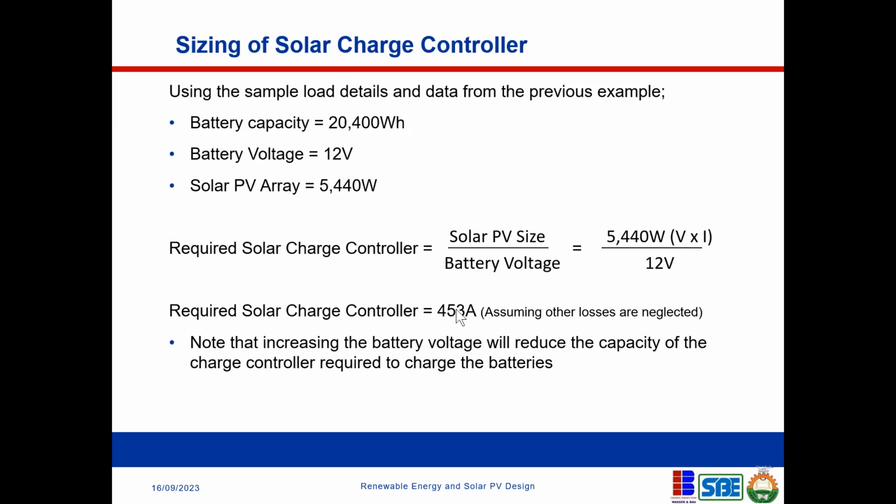That's what it means. And we know that a charge controller costs money. It doesn't come cheap. So if you want to reduce the cost, reduce your charge controller. That's what I stated here: note that increasing the battery voltage will reduce the capacity of your charge controller required to charge the batteries. That is just what I wanted to highlight here.